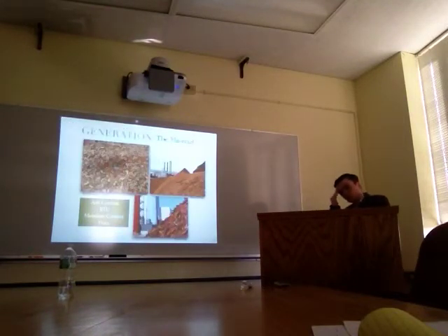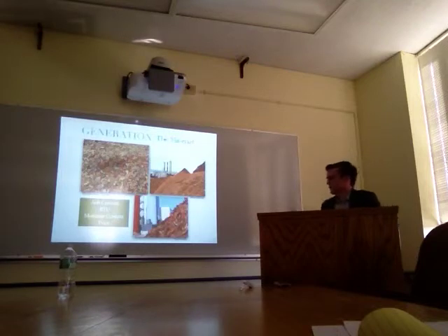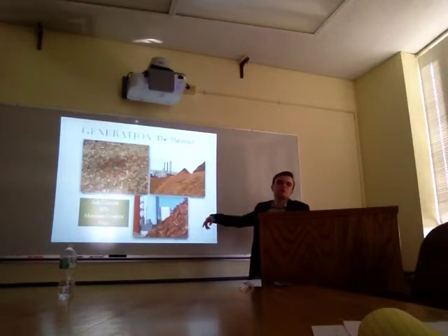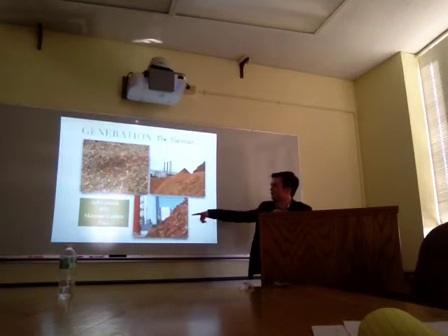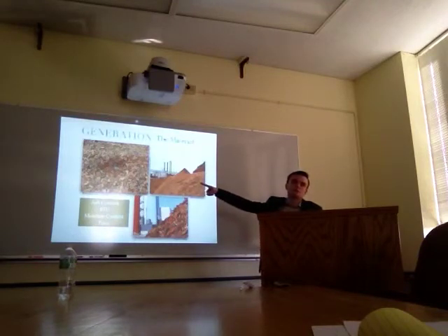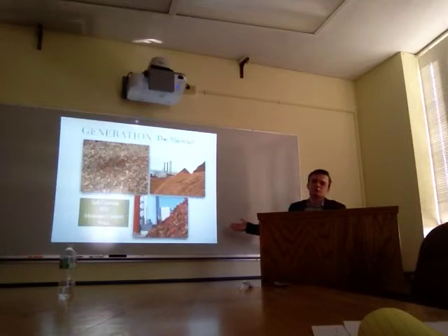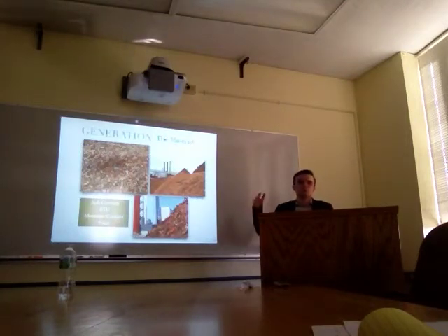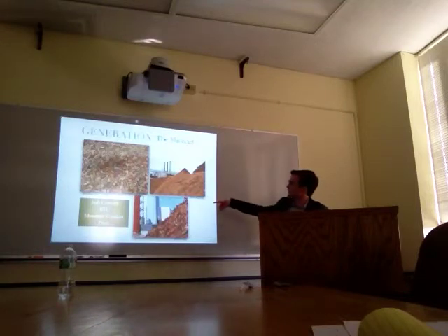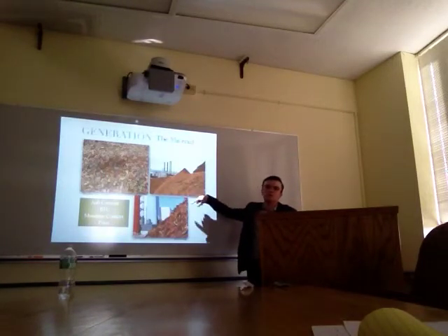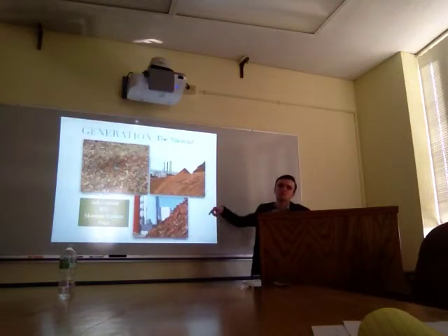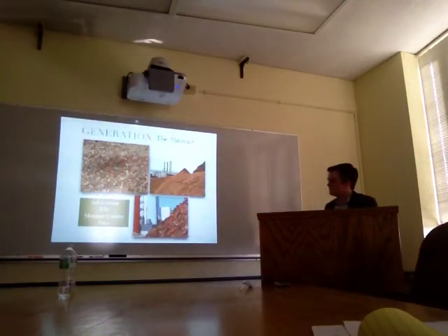This is the actual fuel source they're burning. So they're buying mill waste, which is bark, sawdust from the mills. They're buying hardwood chips. These are directly from the woods. Essentially a chipper, just a mulching machine, drives into the woods. They throw the hardwood in there. Out comes chips. They load it into a truck and they deliver it. And then the power plant mixes the two together. It mixes all of their stuff together so that they have a more consistent fuel source. Because hardwood has a higher BTU, the softwood bark has a lower BTU. By mixing it all together, they get something a lot more consistent.